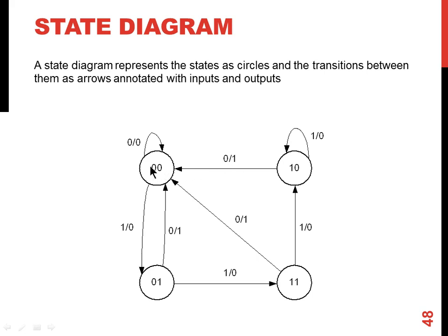1. And again, if you see the idle state, if input is 0, it just stays in the same state until input is 1. So this is the state machine, and it will go from state to state to state depending on the input values. And based on the input values in each state, output is generated as 1 or 0. So this state machine has 4 states.